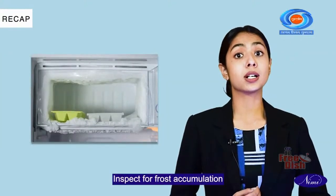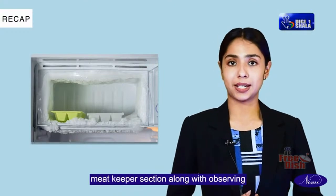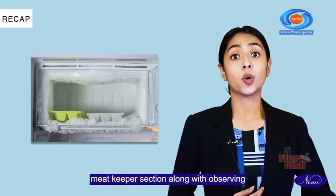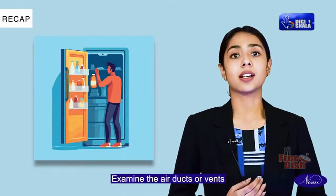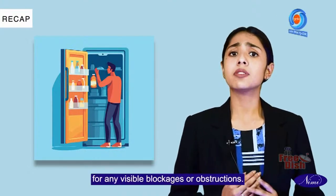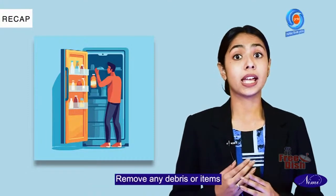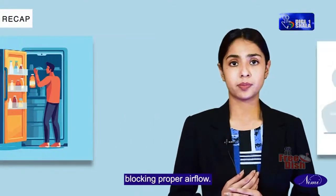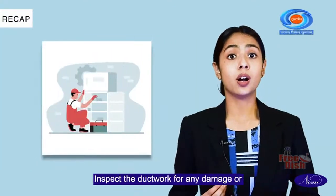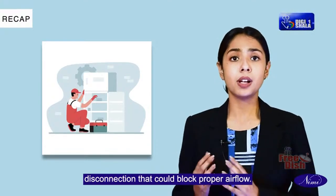Inspect for frost accumulation in the freezer compartments and meat keeper section, along with observing high humidity in the fresh food compartment. Examine the air ducts or vents for any visible blockages or obstructions. Remove any debris or items blocking proper airflow. Inspect the ductwork for any damage or disconnection that could block proper airflow.